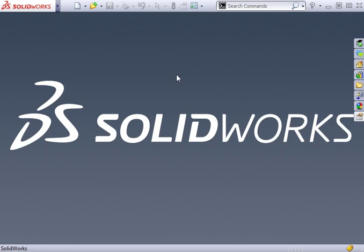The next tab down is the Design Library. It allows me to save frequently used components or features, such as hardware or sheet metal cutouts. I also want to point out this icon here called 3D Content Central. This is where you can share as well as view SolidWorks models with other users worldwide. The File Explorer allows me to look through my documents that are either open in SolidWorks or that can be found on my computer's hard drive or network location.